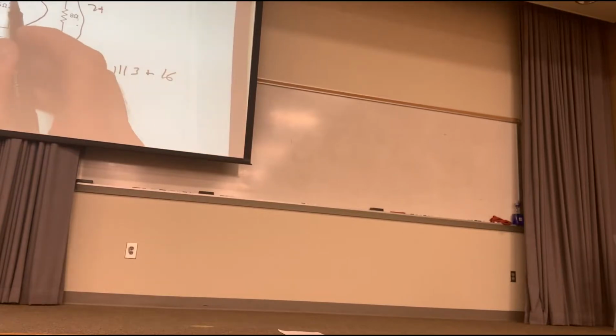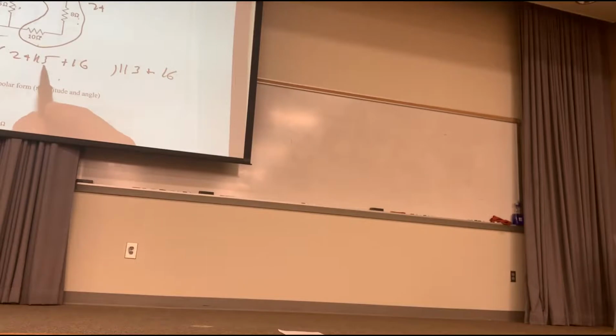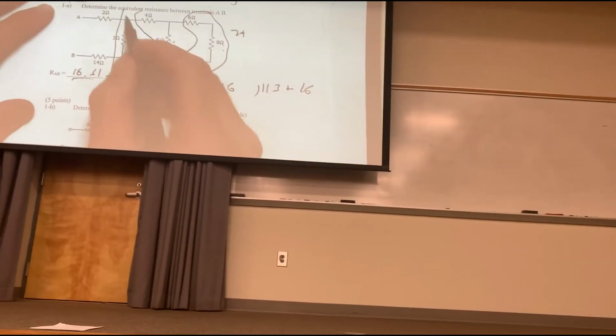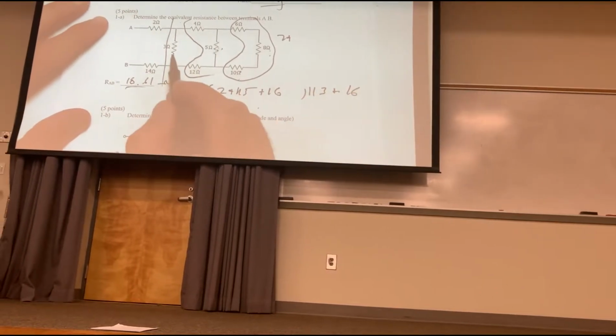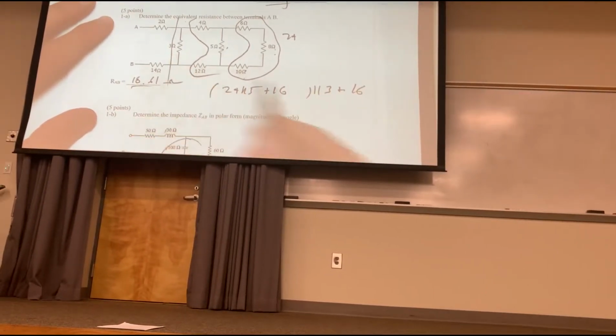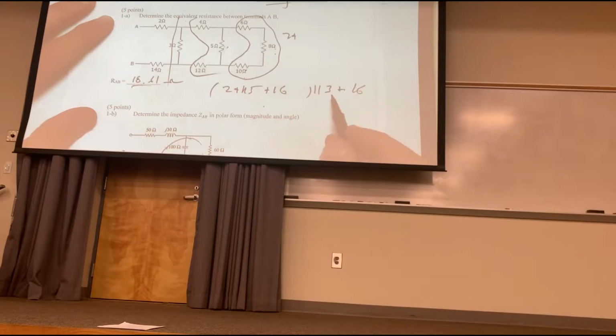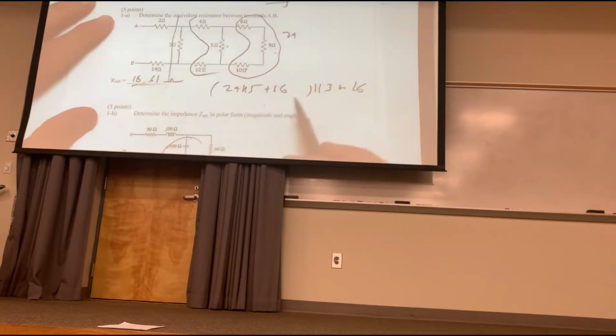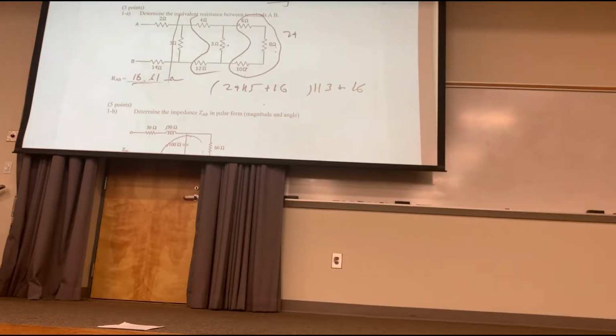Then I've got that resistance in parallel with 4 and 12, or 16. So I have 20.4 in parallel with 5 plus 16, right? This whole leg is in parallel with 3K, or the 3 ohms right here. Do you all see this? I take that times 3, that over 3 plus whatever that is. Finally, I add 16 to that because there's 10 and 2 in series with that. The answer is 18.61 ohms. No matter how you do it, you get that answer. Everybody follow me on this, class?